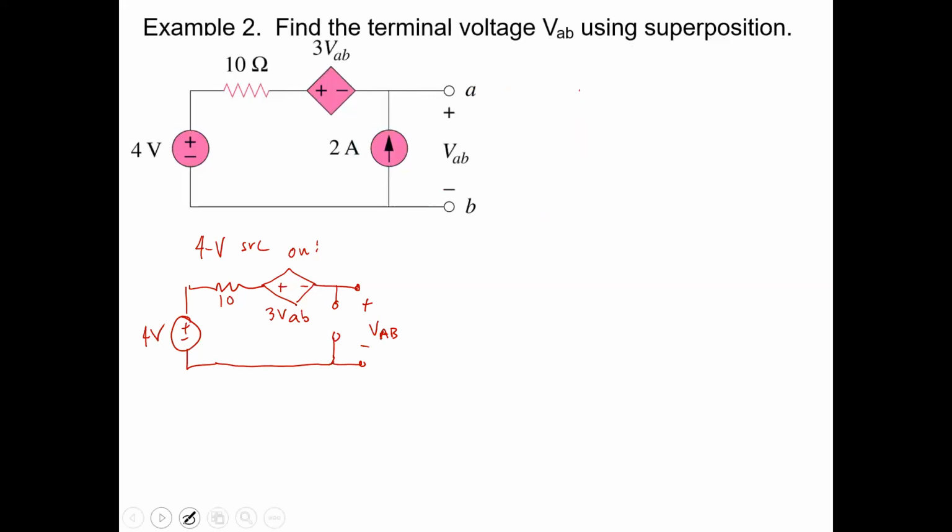So that is a deduction that you have to make when you see a circuit like that. You have to deduce that, because you have an open circuit there, the current throughout that whole thing is zero. You might want to underline that or put a star by it. It's zero, right? Because you have to infer that from the circuit. There's no Ohm's law that's going to tell you that that's zero. It's just that you've got a loop of components that isn't quite connecting, so you can't have current flowing across that boundary. So the I is zero.